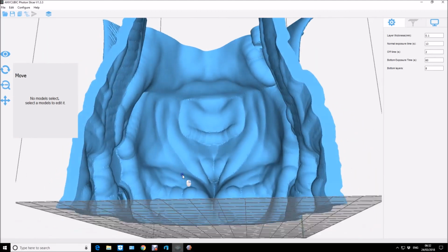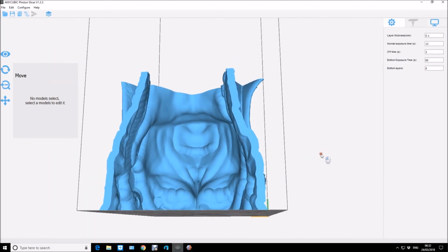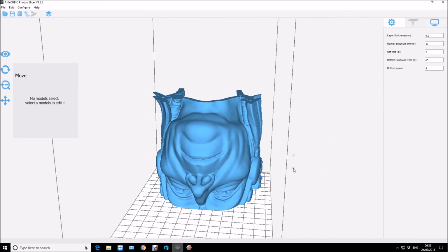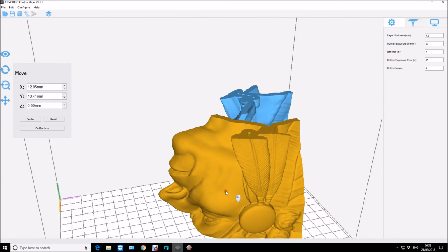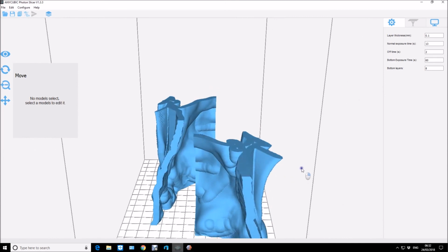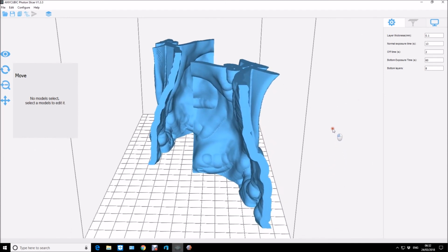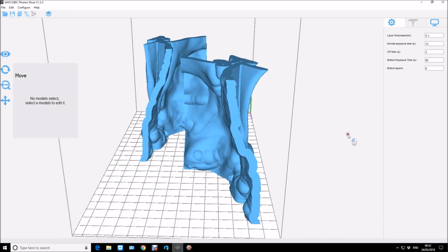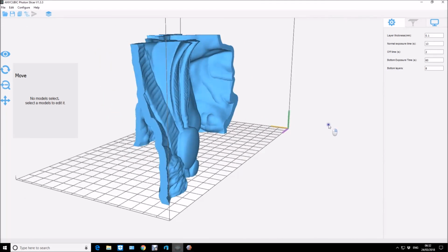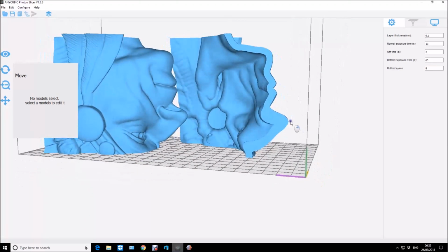Now it works for most of the parts, but some parts you still need to print separately. But you can print more than one part on the base if you wanted to. You could have them split like this. And remember that printing one part takes just as long as printing two parts if they're the same height. But it all depends on how much you want to risk actually on the FEP. I tend to print them one at a time, just makes life a lot easier.